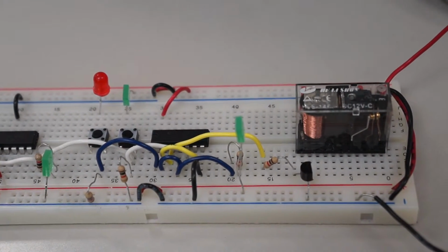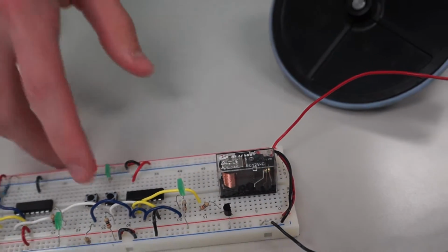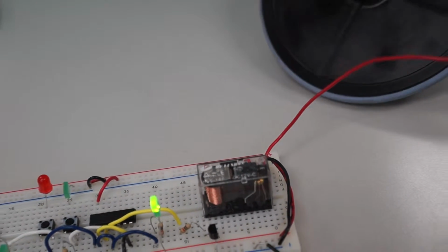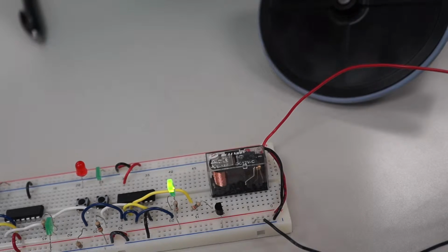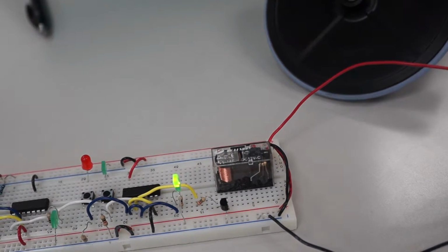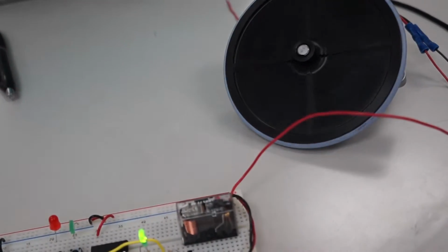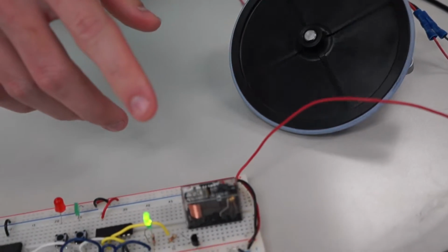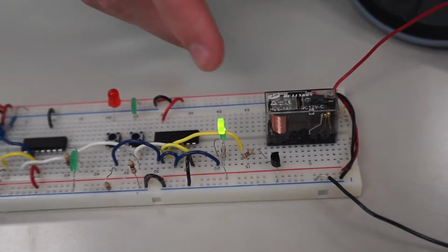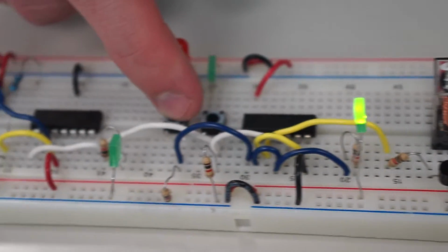As the circuit is cut on, either manually or automatically, the transistor is saturated. It acts like a switch and allows current to flow through the relay, which allows the relay contacts to connect, allowing current to flow through the DC motor. The LED turns on as well because Q0 is grounded, allowing current to flow through the LED, cutting on the LED. If the reset button is pressed, the entire circuit cuts off.